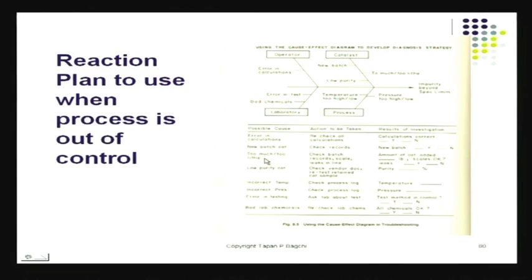Too much quantity added or too little added, check the batch records, check the sheet, look at the scale and so on. Make sure the scale was calibrated, all those things. If that is happening repeatedly, then of course you probably are missing on gauge R and R. That is something you probably should not do. Particularly if you're trying to be a Six Sigma production process, you should not really do that.